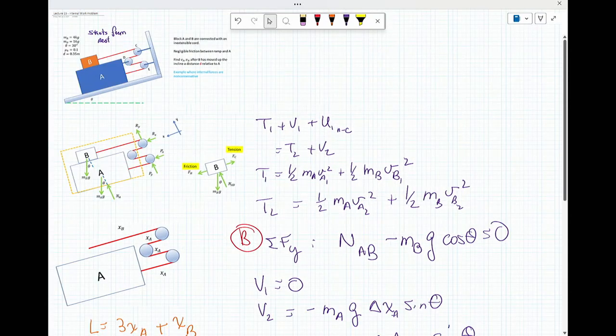And we went through some effort here just so you remember. It starts from rest. We'll define our initial datum as 0. And so the only thing left are the non-conservative work terms that come from the slip between B and A. So we have T1, T2. T1 is equal to 0. T2, I don't know yet. Then you calculate through, you figure out all of the terms.